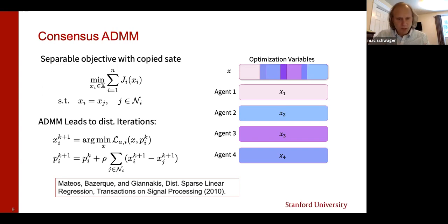And then robot i performs what's called a dual ascent step. So here the p variables are the dual variables that impose this equality constraint on the states with neighbors. And you can run through a bunch of math and show that a gradient ascent step on the dual variables reduces to this very simple form. And this requires the decision variables from the neighbors in the neighborhood. So it requires your decision variables, x_i, and then also decision variables, x_j. So this is where the communication happens.